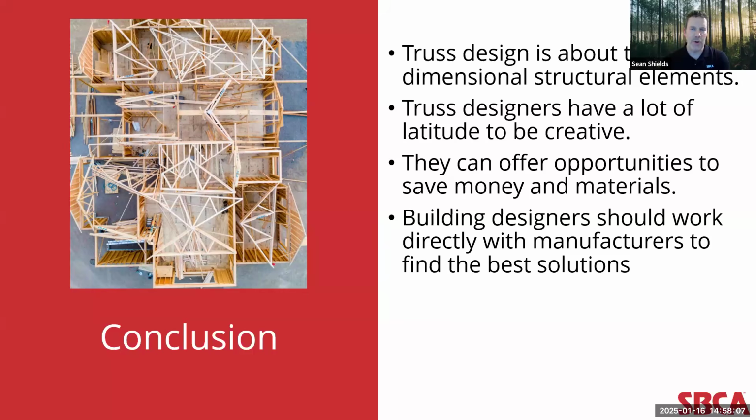I'm going to end with just a few observations along those lines. The truss design process primarily concerns itself with the development of two-dimensional structural framing elements within a three-dimensional roof or floor system. So the building designer dictates the overall shape, and determines the paths that the loads will flow through the structure from the peak down to the foundation. The truss design drawings, though, graphically illustrate each truss for building designers and building officials to make it easier for them to review the individual trusses in a review process.